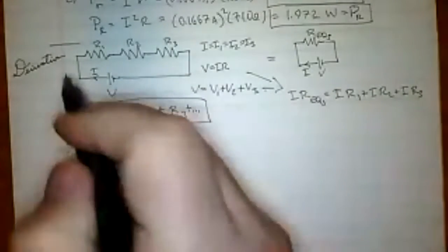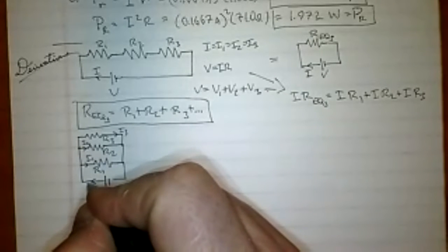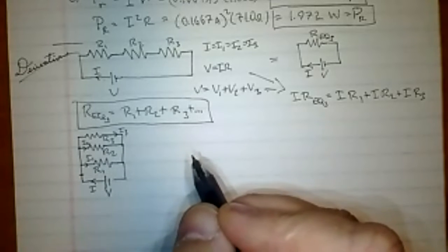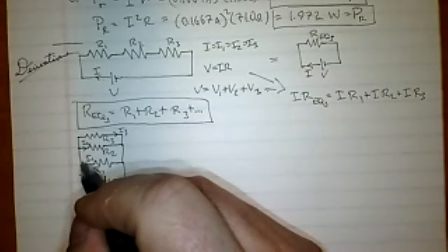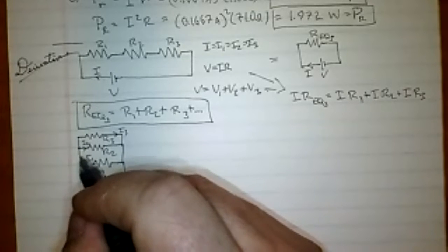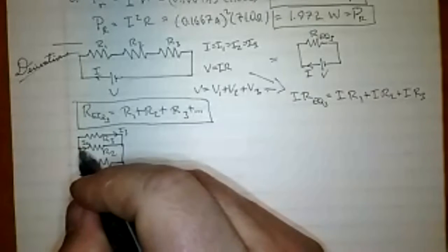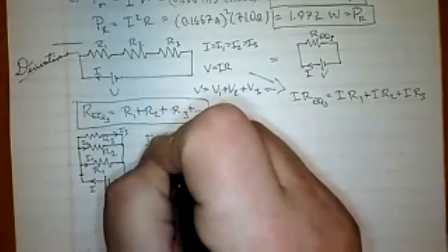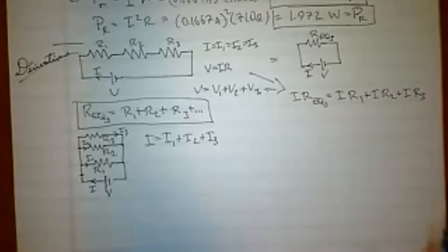What we've also learned in labs, hopefully by now, is that this current is basically a certain number of charges going past, say, a certain spot every second. But when it gets here, it's got a choice. Some number of them will go here and some number will go there. But the total number, this one plus this one going every second, has to be the same as that. Similarly, when it gets here, it's got some number going here and some number going there, so that what you ultimately find is I has got to equal I1 plus I2 plus I3. That's just conservation of charge. Does that make sense to everyone?